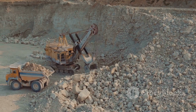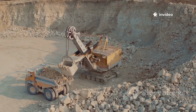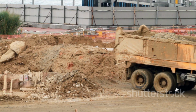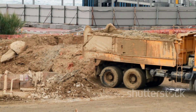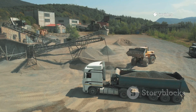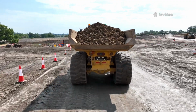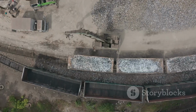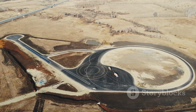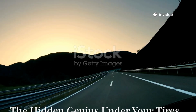Then, a large cut produces 80,000 cubic yards, but the nearest fill is 4,000 feet away. Overhaul territory. The diagram calculates the overhaul cost, and the team assigns their biggest trucks to handle it. Finally, after balancing as much as possible, the remaining deficit is filled from the borrow pit. The diagram shows exactly where every load goes. By following this plan, the contractor moves millions of cubic yards efficiently and economically. The mass haul diagram turns a chaotic landscape into a smooth, ready-to-pave roadbed.